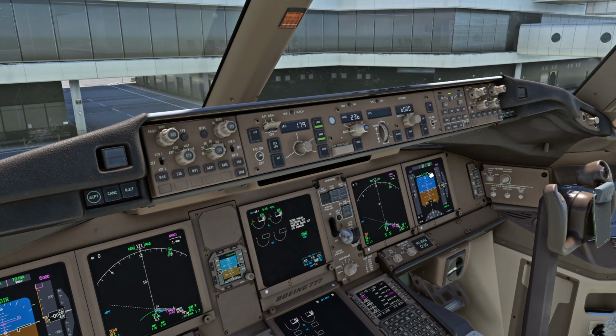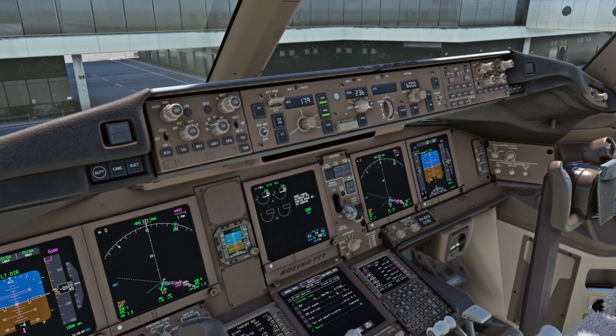So let's say that the cabin is ready and the cabin secure is given. The gate is removed, the ground crew is ready to go. Release parking brakes. Again, they want us to release parking brakes. The bypass pin has been inserted. We've done all the checklists, we've done all the flows, so now we're pretty much ready to go. So we can do the before start checklist.